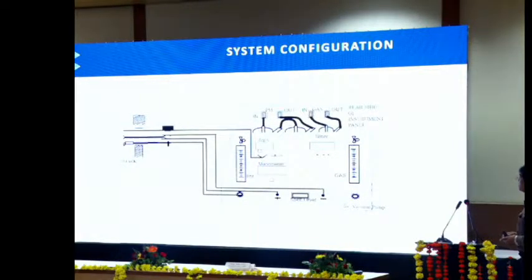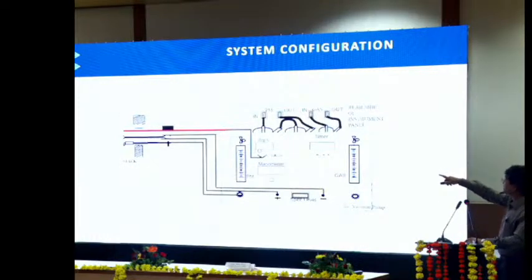Now just to make things simpler, we have divided the whole stack into 3 different parts. The first one is temperature, the second is velocity, and the third is the sampling front. So I'll be taking them one by one. See, this is the probe with the red mark. This is the thermocouple probe in order to know how much is the temperature inside the stack.